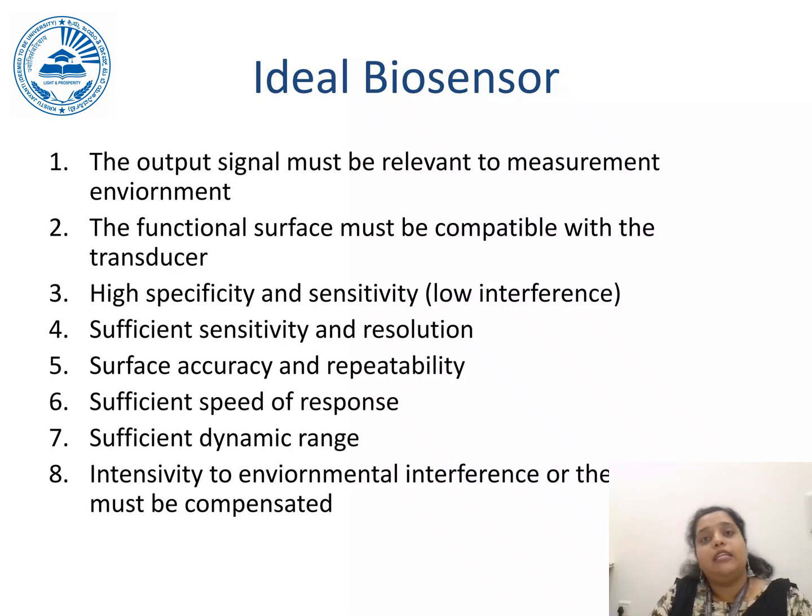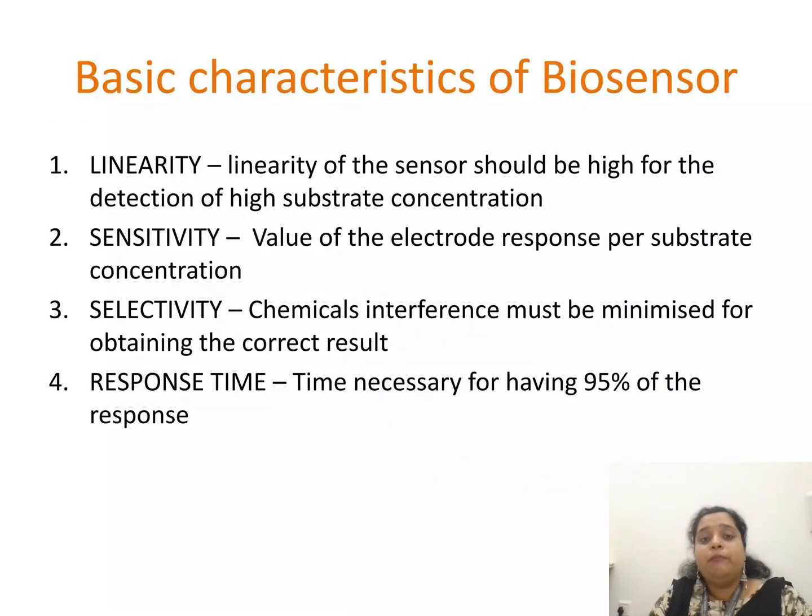First thing, the output signal must be relevant to the measurement environment. Second, the functional surface must be compatible with the transducer. High specificity and sensitivity is required. Sufficient sensitivity and resolution is required. And fourth, and the most important thing, sufficient speed of response and sufficient dynamic range is required. Insensitivity to environmental interference should be compensated. Clear?